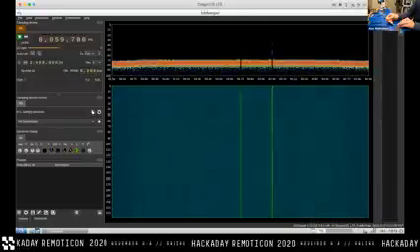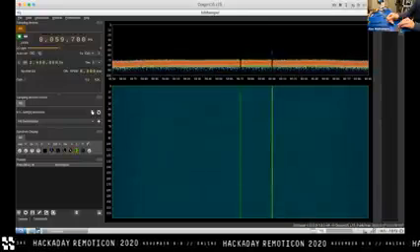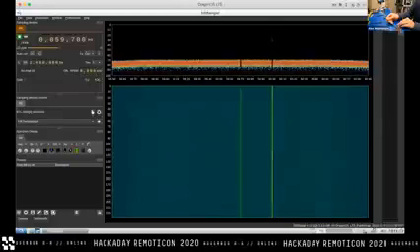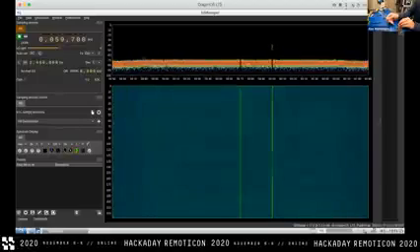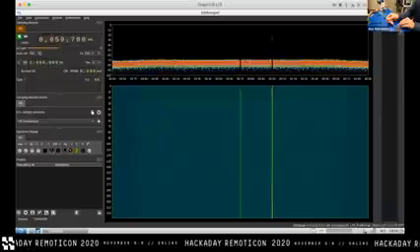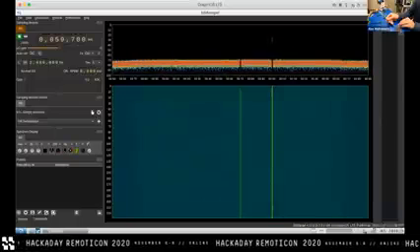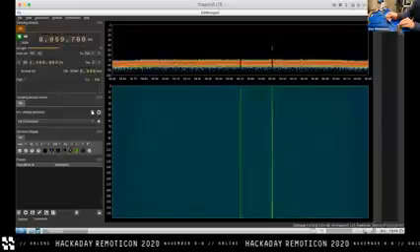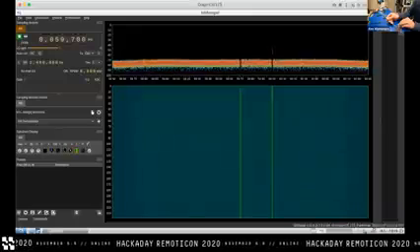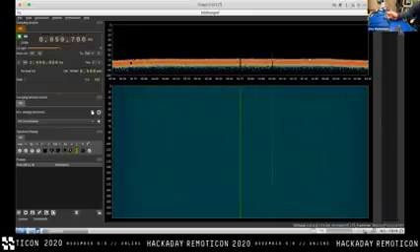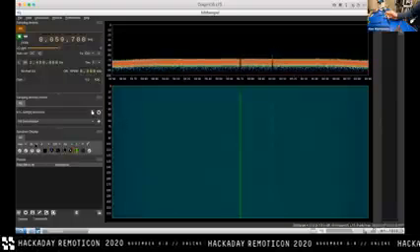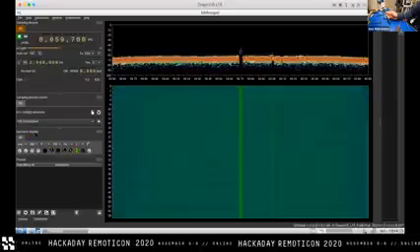For any particular case, you basically have to feel around for the combination of settings and tools that work best in that case. What we can see as we get close to this little capacitor that's right here, that capacitor certainly has some serious current going into it at that 60 megahertz mark. And obviously, if I pull away, that line goes kind of dim. If I come in really close, that line is nice and bright. We can really see something going on there. And basically pinpoint which pin it is by figuring out where it's the brightest, where we're moving our wand.